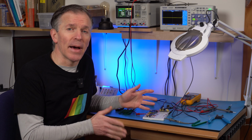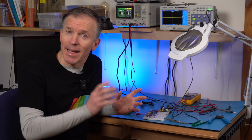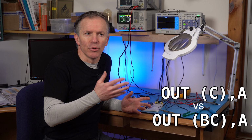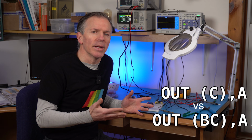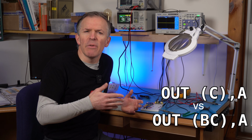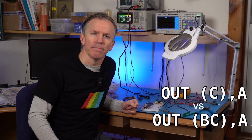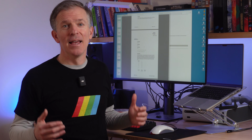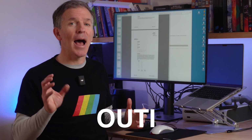So this is great. We finally know what outCA does exactly, and the Zilog manual was correct. So now the big question is, why is the instruction written as outCA instead of outBCA, which is really what it's doing, and how come B isn't even mentioned in most of the documentation? The answer, I'm afraid, will cause us to go one step deeper into this mess. The answer is the instruction outI.